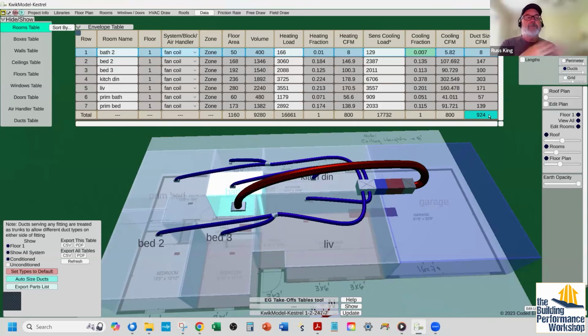That's why every time I designed a furnace system back in the day, it'd be half-inch static pressure we designed to, and I would design to 400 CFM per ton. They would go out and measure it. The static pressure would actually be a little bit better and the airflow a little bit higher every single time, because of that little roundup that Manual D does.